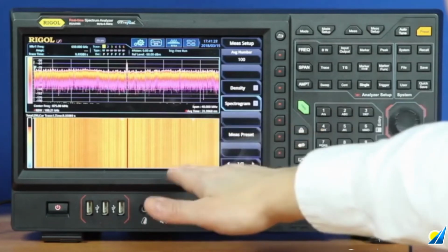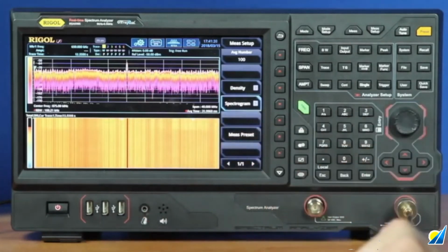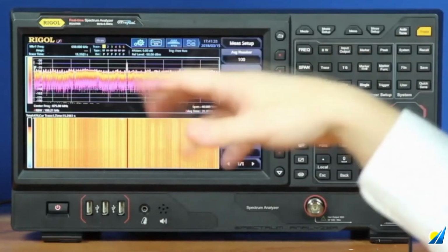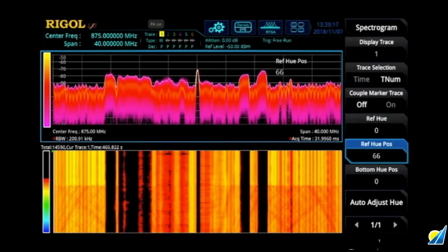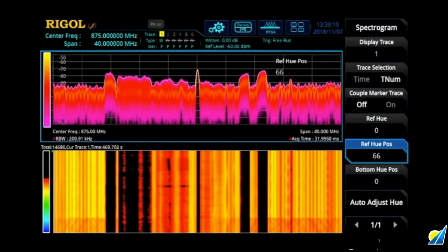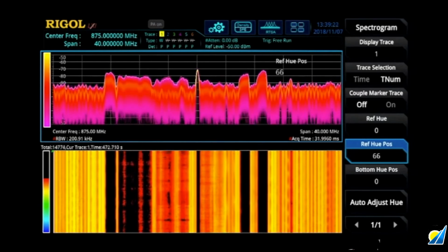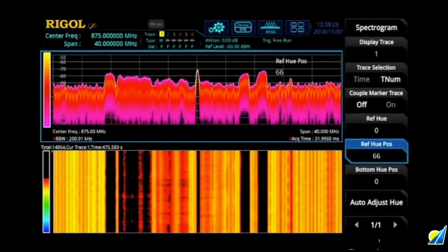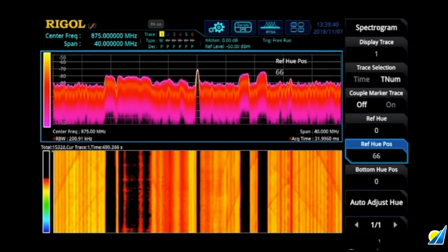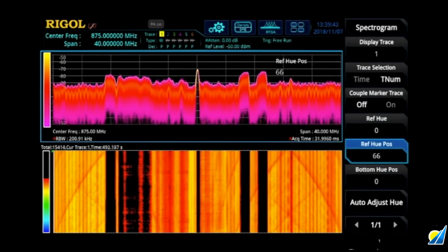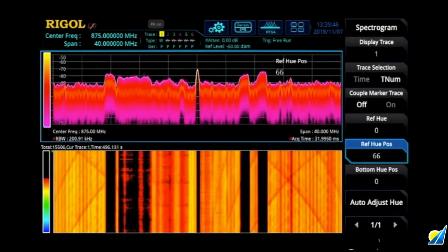We can see some subtle effects here as this chip that we're focused on really has a reset and then has some frequencies that move around in this span that are frustrating us. We take a closer look, we can see right there a reset occurs and the power drops across this whole spectrum. Now over the next 30 seconds it builds again and resets, and this is a continuing, renewing cycle. If that was annoying us from a pre-compliance standpoint or from a functional standpoint, we could use this kind of real-time test with super accurate RF measurements to isolate the ultimate cause of what's causing that dithering frequency and that power building, and do something about it.